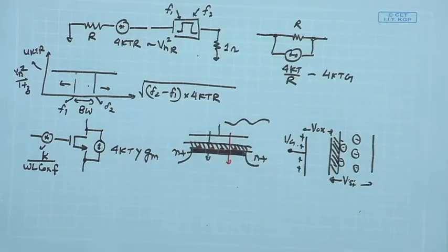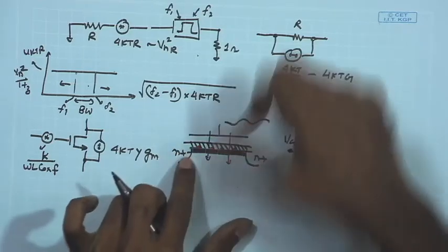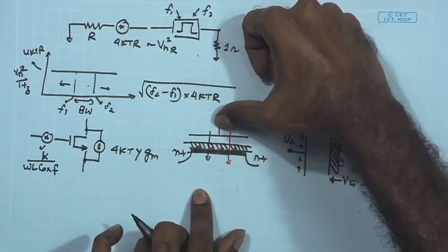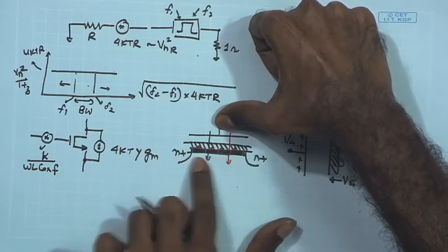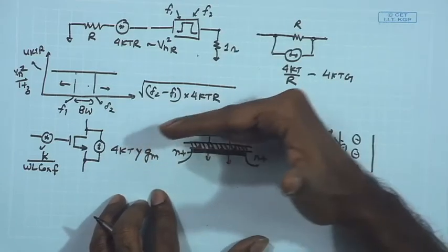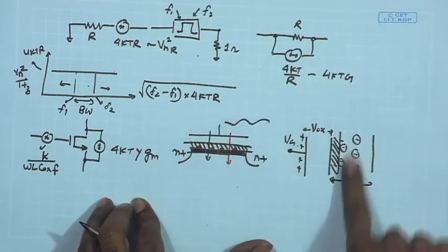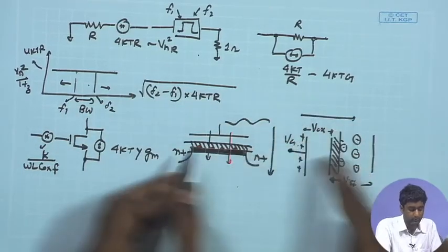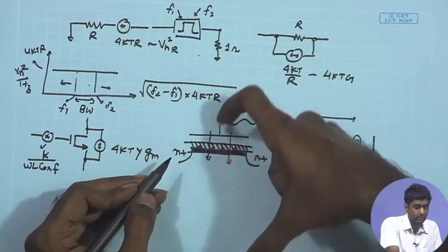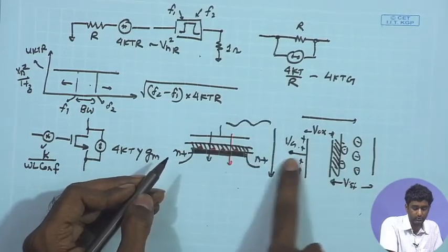So, in the silicon, when you are applying the positive potential at the gate for the NMOS, we know that the p type substrate of the NMOS will have a lot of holes, the holes will get pushed down, and as a result you will produce a depletion region. I am drawing the vertical view here, looking down into the MOSFET in the vertical direction.